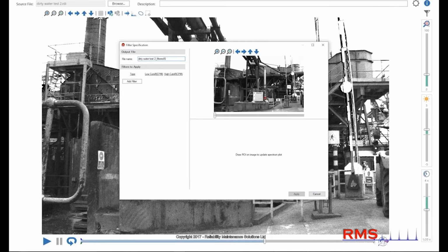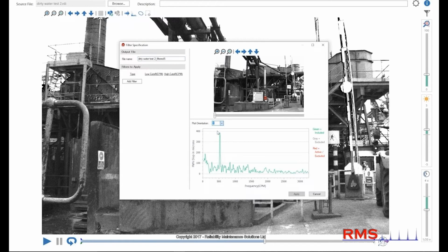And when you do that, faults manifest at particular frequencies, so it gives you a particularly interesting look at it. So here we're going to isolate that one frequency on the pump, and demonstrate how you can isolate that one frequency.